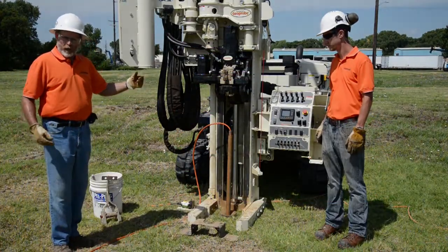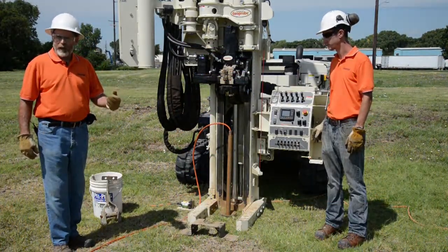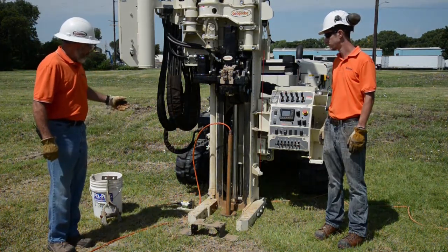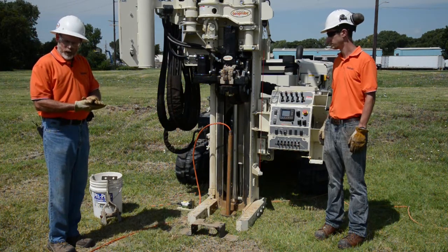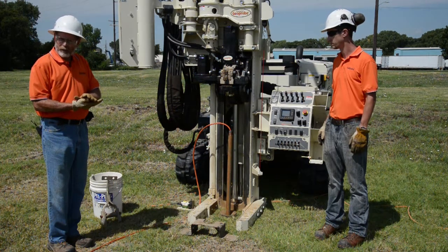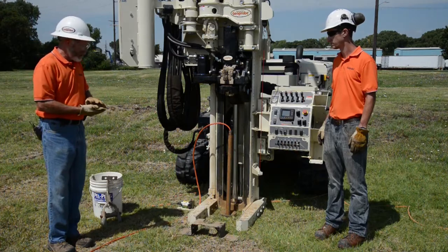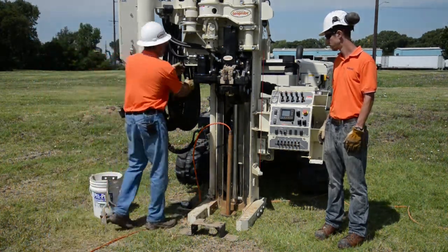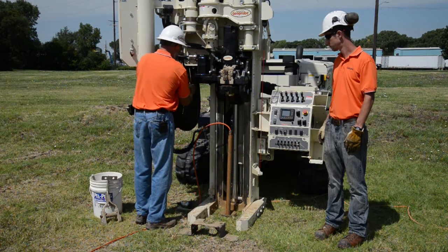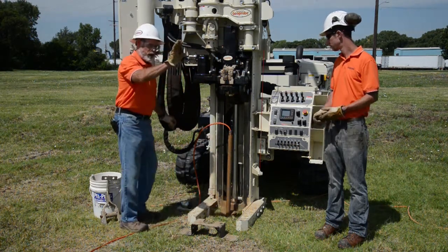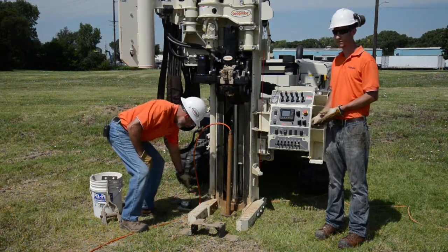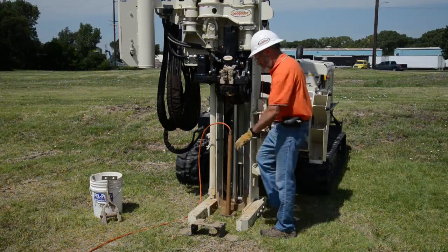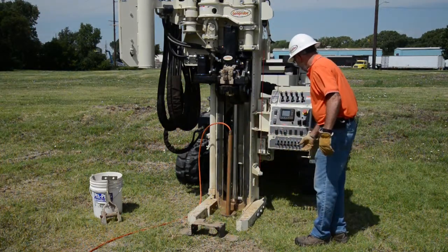Okay, so we're now a little over 60 feet, about 61 feet on the electrical conductivity log. So we've run into the shale and gotten refusal at the shale bedrock here, as I said, just over 60 feet. So now we'll disconnect the string pot and get it out of the way. We stopped the log on the software. So what we'll do now, we have the rod wiper on here. So we're at the weldment to hold the rod wiper in place.